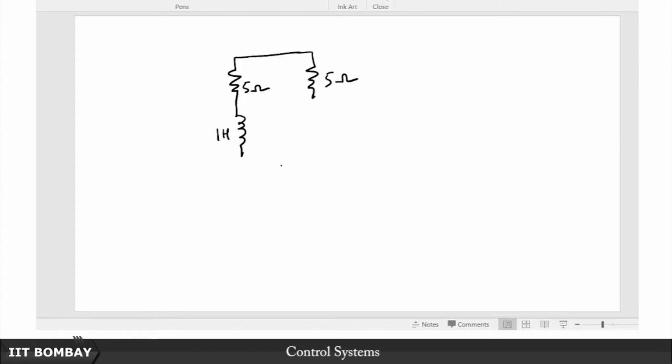Suppose we are assuming a loop current in this direction, then this is the direction of current flow. So this is the polarity of the inductor. Remember, it is a passive element, so current flows from the positive terminal to the negative terminal, and this will oppose this, but that is only under the assumption that this is IL0 minus times L. Now L is of course 1 here, so I could have ignored this L, but let it be for the time being.